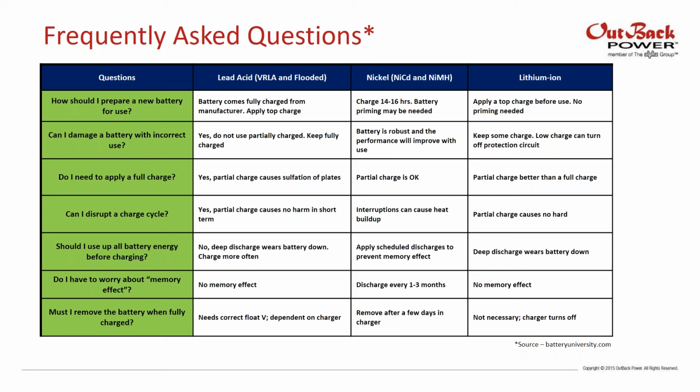Can you damage a battery with incorrect use? Yes. Hopefully I've impressed that upon you in the last half hour. It is really hard on a battery, especially lead acid, to go to really low state of charge. Lithium you can, but again, it's usually recommended that you only go to 80%.